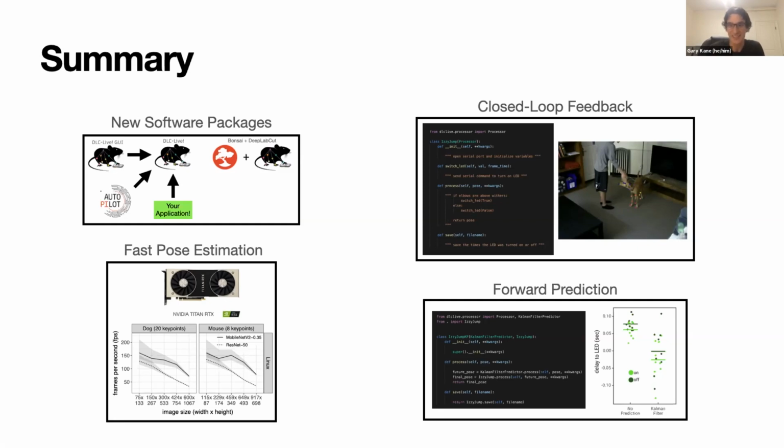The velocity is the difference between this frame and the frame before, and then the acceleration is the difference between the velocity measured on this frame and the velocity measured on the previous frame. Once we have those three values, then it's a quadratic approximation. So we're using this acceleration and velocity and extrapolating forward to predict where we think it's going to be based off its current position, its rate of change, and the change in the rate of change.